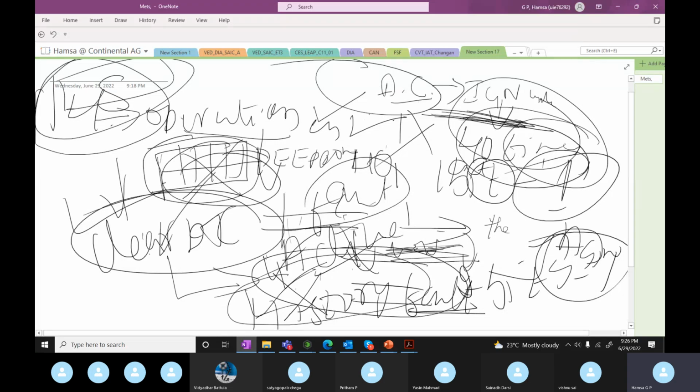What happens if a fault is set actively? The system reads the faults again every 100 milliseconds. After reading, whatever fault conditions still exist, those faults will be set in the memory again. Whatever were history faults, which were there before but whose condition is now removed, will be removed from the memory.